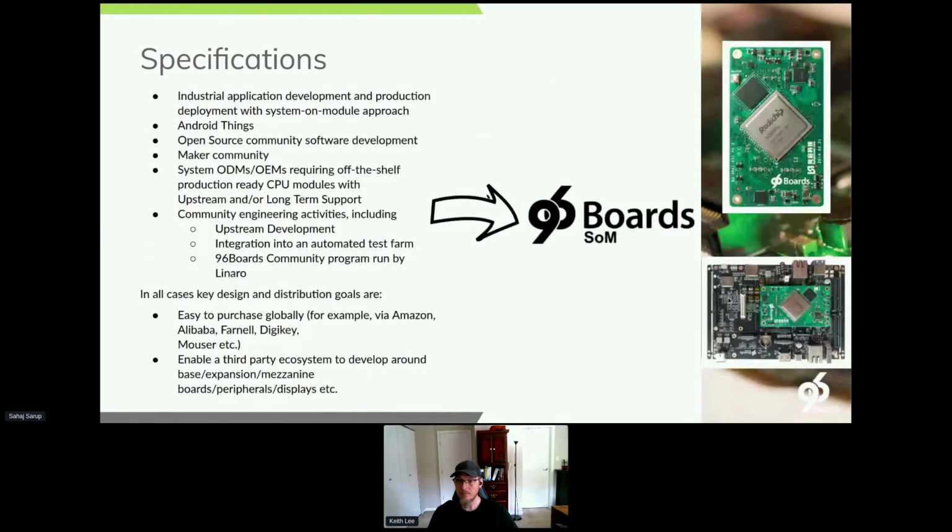Today we are going to focus on the SOM spec based product, and these are SOMs, or system on modules, that you can put in your final product. Our SOMs are designed with industrial grade connectors, so they can be used in high vibration or harsh dust environments, and the connectivity between the SOM and the baseboard should not be affected.